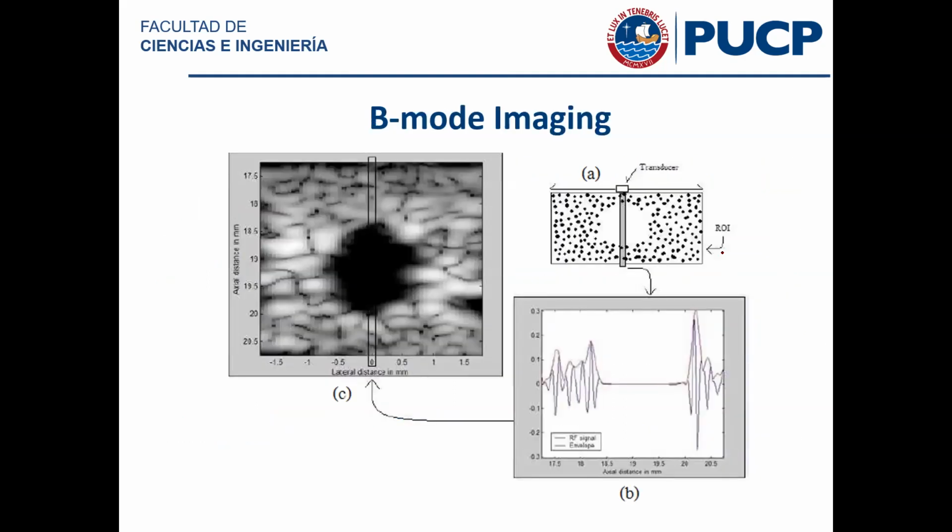And this is what the process of constructing an echographic image would look like. You have one transducer, and you have to make sure that it transmits an ultrasonic beam that's very, very narrow laterally. So you place a transducer with a very narrow beam on top of a medium that you want to create an image of, in one location, and you produce a transmission.